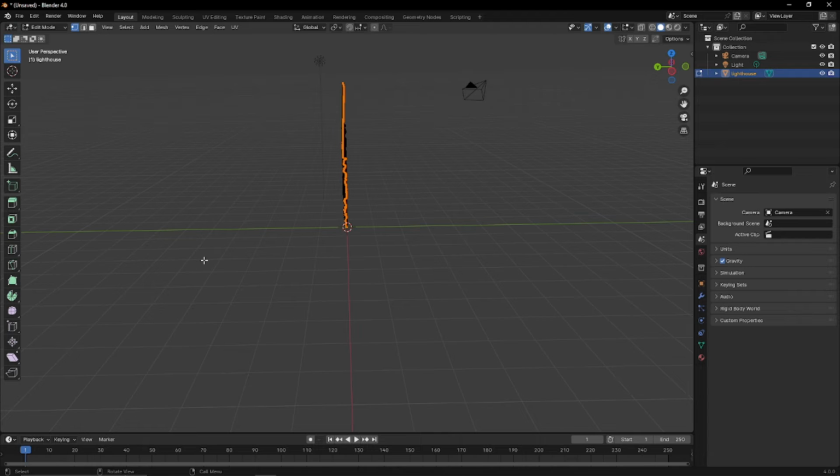Okay, and that's just going to select the outer edge of it. And then what you want to do is hit E on the keyboard, and you're going to see your cursor change. And then you use your left arrow button and just hit that a few times, and that will extrude that. Do you think you have a close enough edge there?